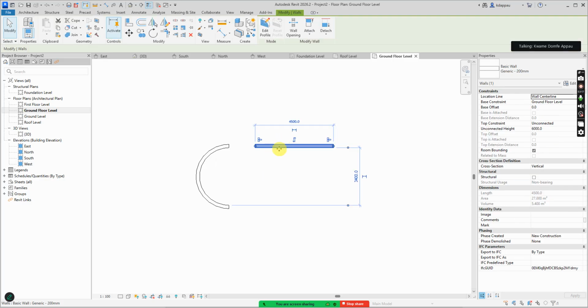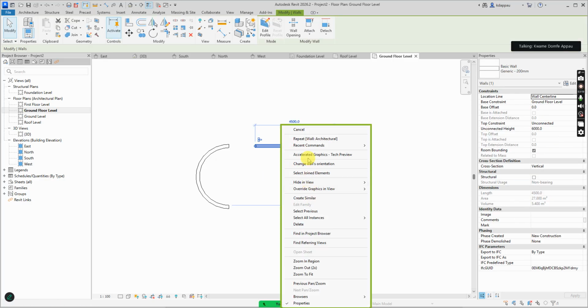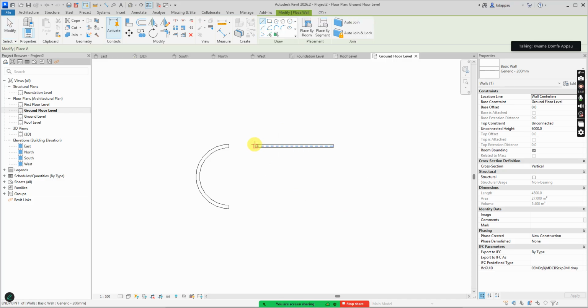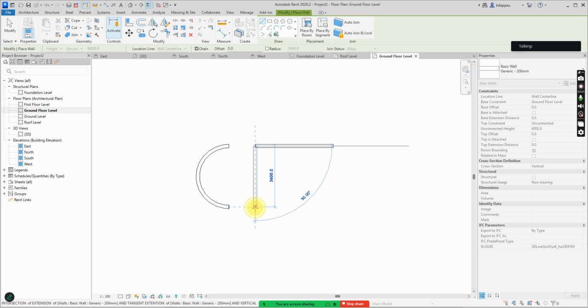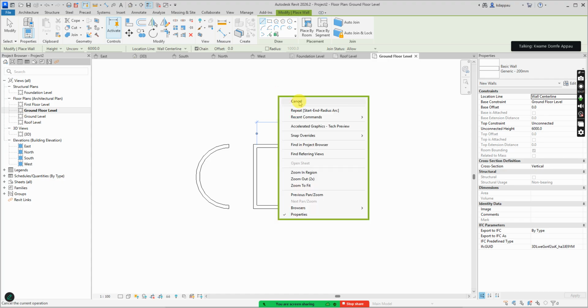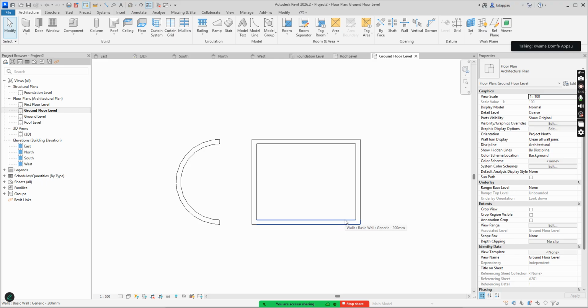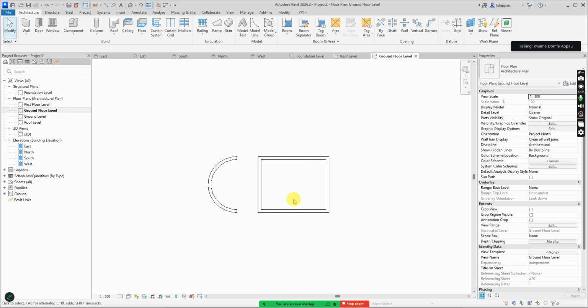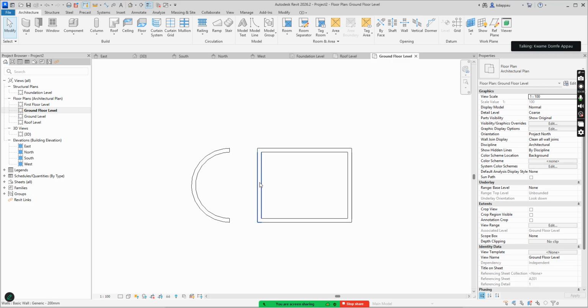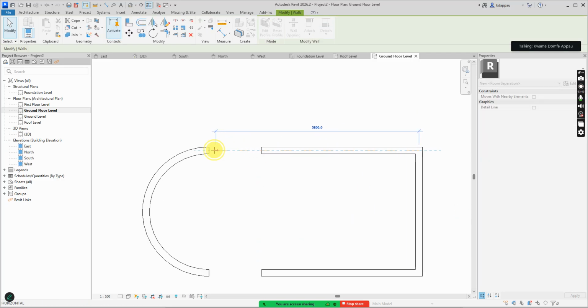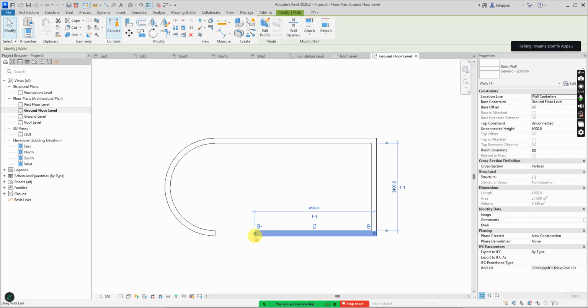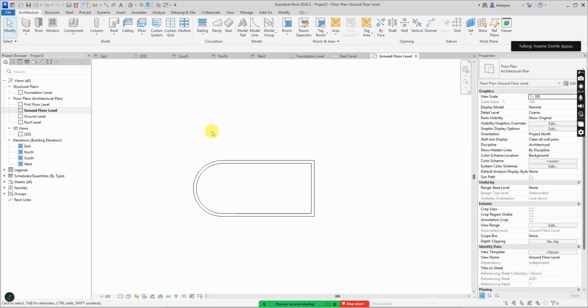So if I take this wall here, and I create 4 of them, create similar. Start from here, come to the end here, go here, come here. It is 4 walls that I have drawn to get this room defined. So I can add more walls to create more spaces depending upon the design requirements. I can take this wall, delete it, take this wall, extend it to come and meet this one, take this wall, extend it to come and get this one to create this shape.